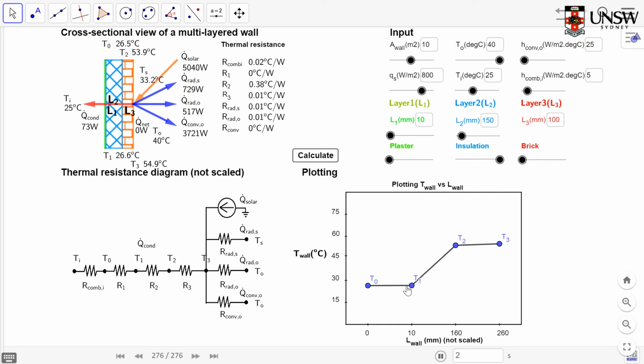Alright, so after you've set your parameters, you have to click the calculate button in order to calculate what the temperatures are at each point along your wall. And you can go and play through your various temperatures if you wanted to alter the temperatures, and just click calculate again. And just have a look at how that affects the temperatures that are moving from the exterior to the interior of your building across these materials.